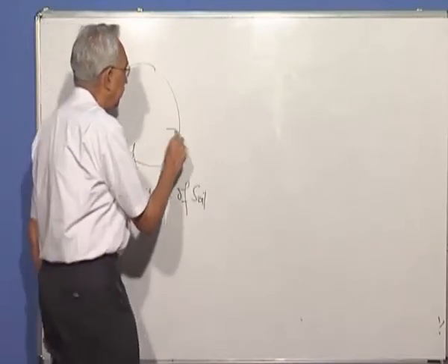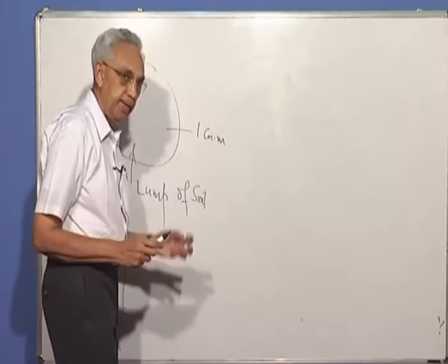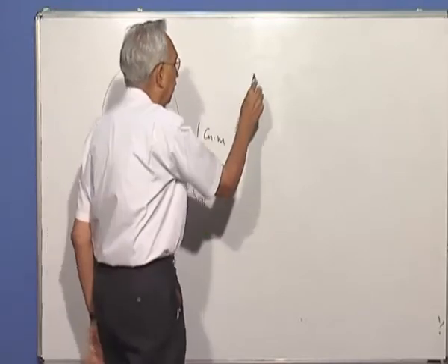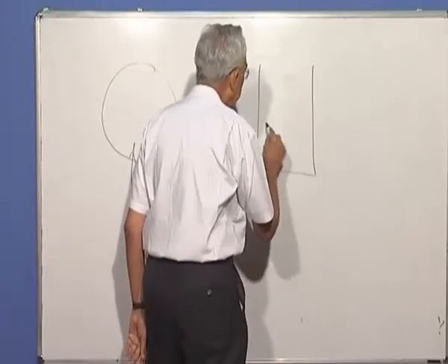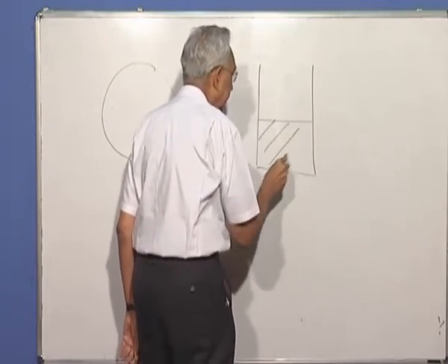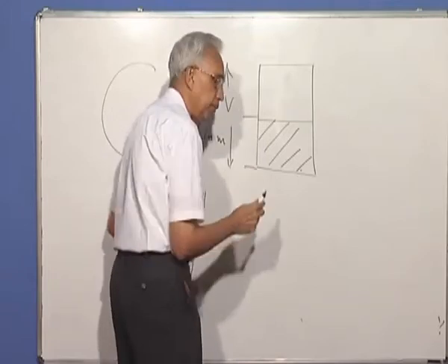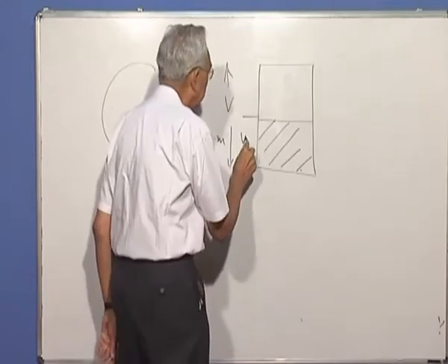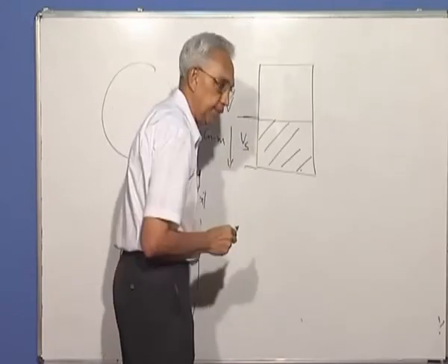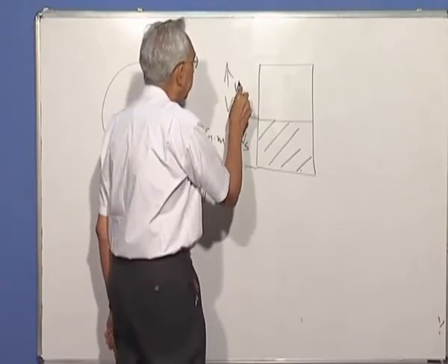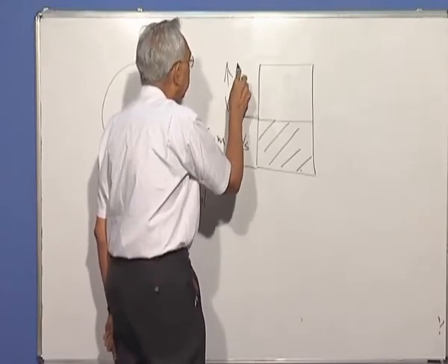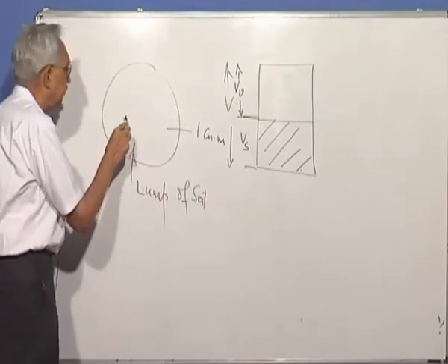Let us say it is 1 cubic meter. Can I imagine you have taken away all the soil particles and said the grains are put in here. The total volume is V. So I say, if I can find out the volume of all the solids, volume of the solids is here. The remaining part I'll say is volume of voids, which is nothing but the spaces between grains.